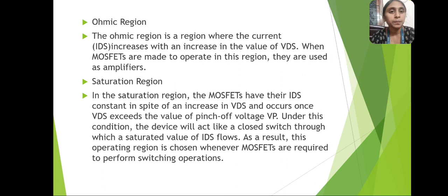Saturation region: saturation is the region of the MOSFET where IDS stays constant with an increase in VDS. When there is an increase in VDS, at a particular point it acts as a constant IDS. This occurs once VDS exceeds the pinch-off voltage VP. So when the pinch-off voltage VP is exceeded, we enter the saturation region.